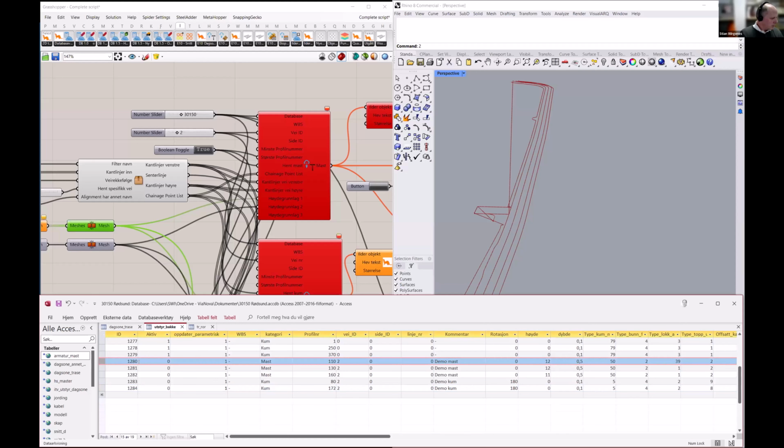And we have created this, this is mast storage, Norwegian for light pole. And I have said that I want to place that one in profile number 110 at road number 2. On side 0, that's the same as Quadri use. 0 for, what will it be again? 0 for the left and 1 for right. And we used the Quadri line 0, just a comment.